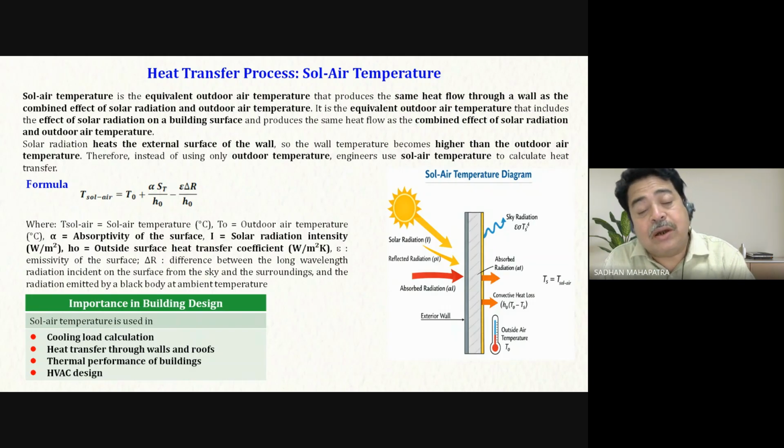So that's why in our solar passive building case, when we were putting the design parameters, one was the absorbability. Aperture, absorber. Now absorber means this wall. This wall's absorbability will depend on what kind of surface you have. If it is a very polished surface, that means absorbability is low. If it is a dark color, your absorbability is high, and that depends on this alpha.